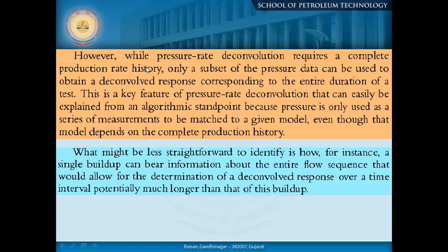While pressure-rate deconvolution requires a complete production rate history, only a subset of the pressure data can be used to obtain a deconvolution response corresponding to the entire duration of the test. So this is the advantage. When we are doing so many consecutive tests, sometimes we may have a skin at one time, but after some time your skin has been removed, so the third buildup may be very good. We'll see today, with some of our synthetic examples, how depending on the variation in your response or on the time of the test, you will get different response functions.